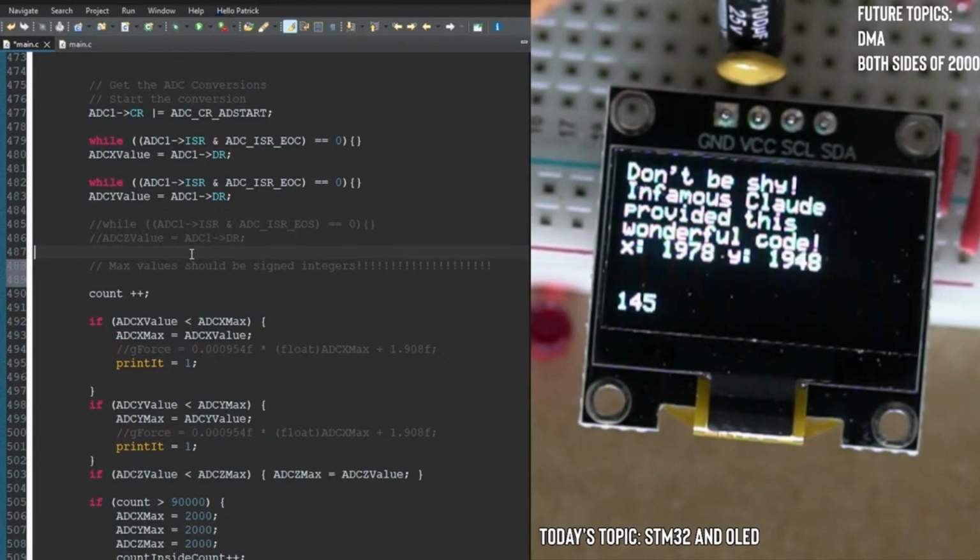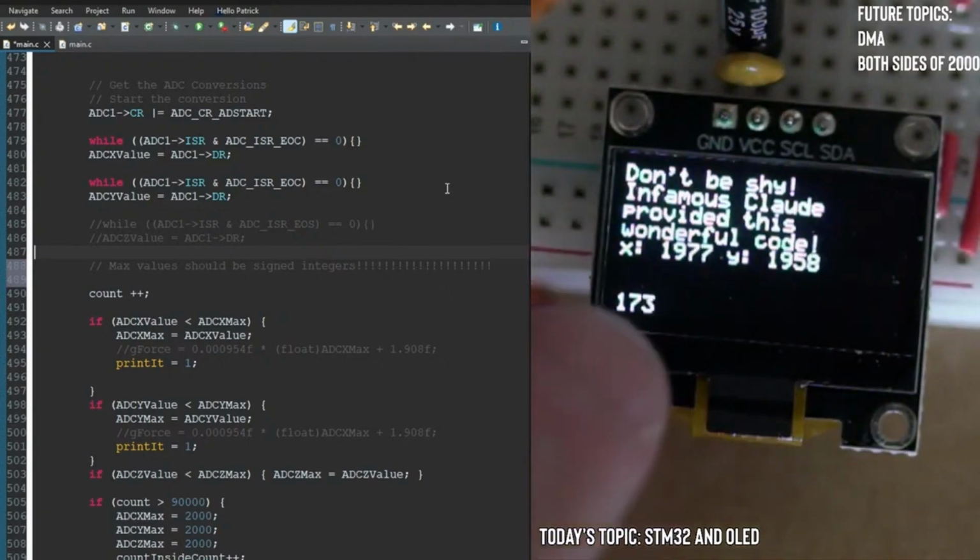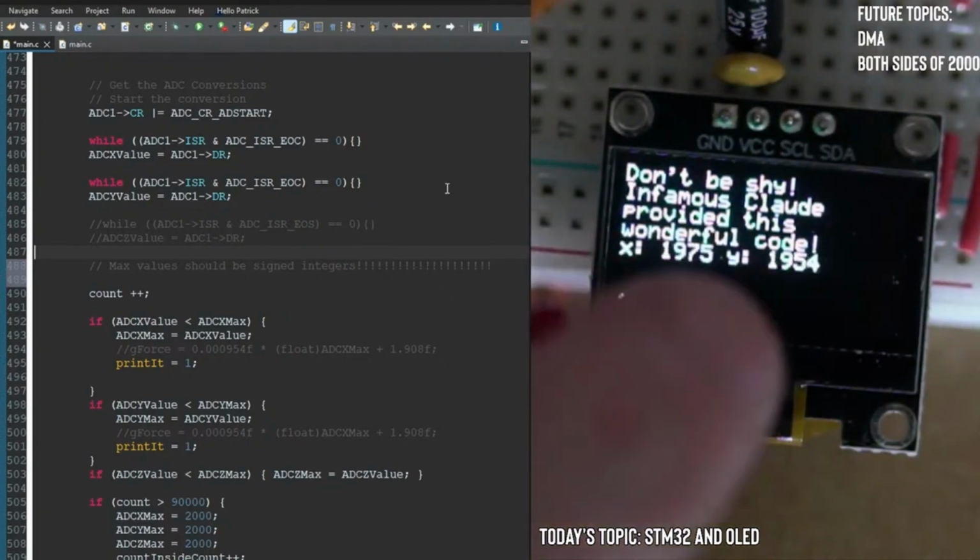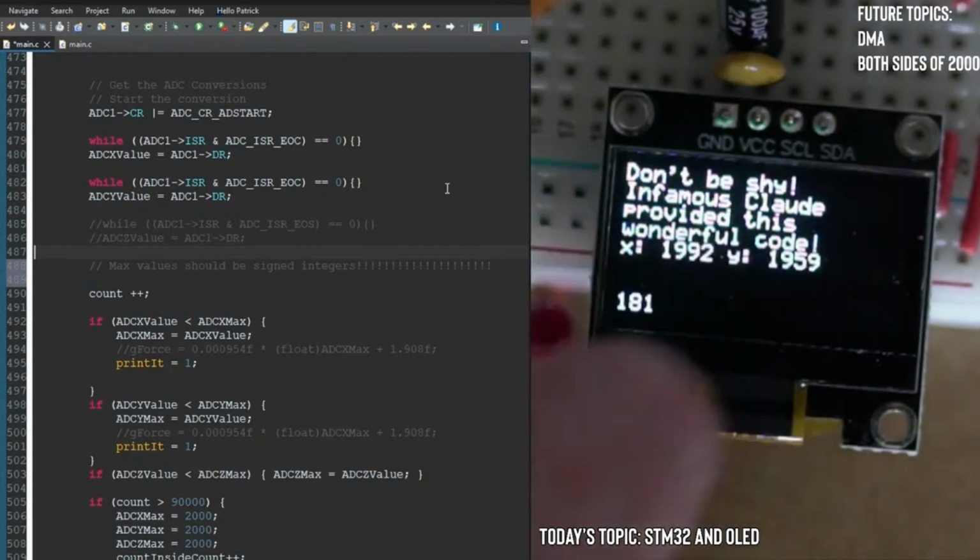Lars Christensen is stating that if it is a 12-bit converter and 0 is in the middle, you just need to XOR the most significant bit to get signed. Okay, yeah, we can do that. We can explore that the next time, but we can see that it's incrementing at a pretty good rate. So this could be a good way to get values in a time we can still see them.